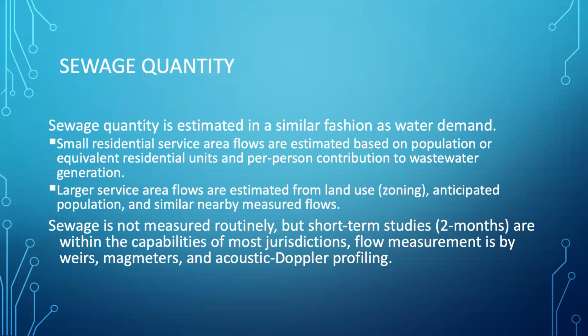The technologies involved are mag meters, acoustic Doppler profiling, if you can figure a way to keep the toilet paper and other sticky things like that that are in sewage from wrapping itself around the sensor, or install a very low weir in a collection line and measure the water surface elevation and apply a weir equation. Those are all commonly done.